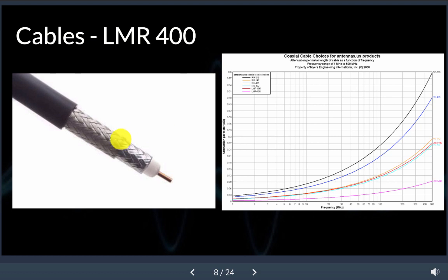These cables are going to possibly have ice buildup on them, which will weigh them down and could cause the outer conductor or the center cord to break or become disconnected from the connector, or to short across each other. They also face wind, hail, all kinds of damage.